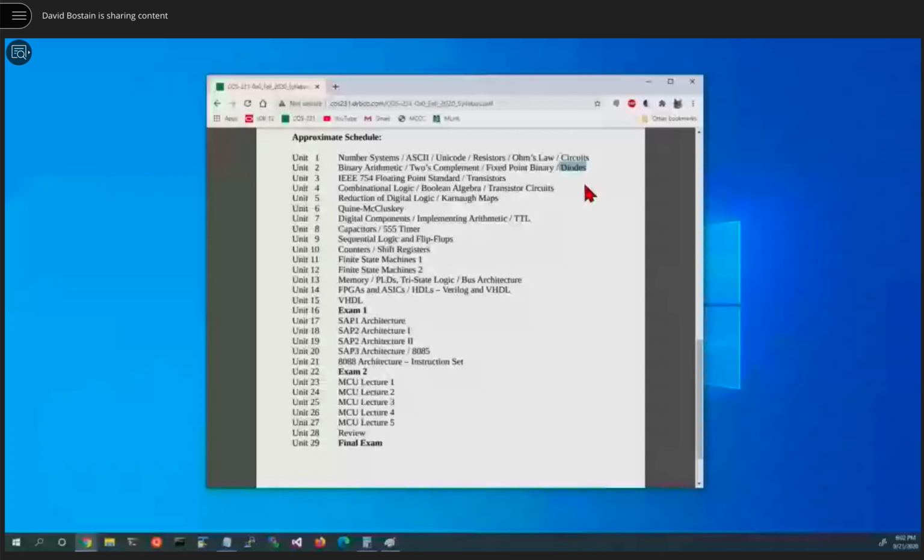Can't do the problems if you don't have these numbers memorized, or at least quickly referenceable in your notes. Would that be 2.1 volts? Right, 2.1 volts. So the thing we know about diodes is they can go in only one way and have current flow through them correctly. And if it's a regular diode, when it's forward biased, it's going to have 0.7 volts across it.